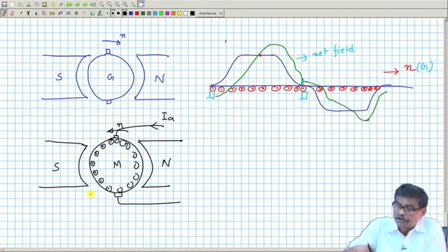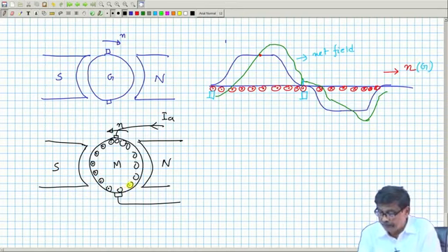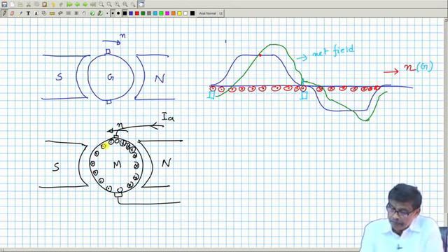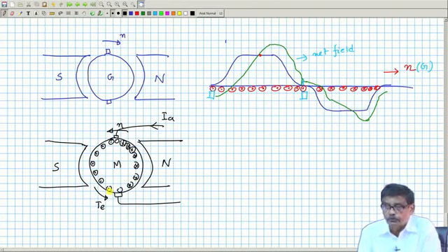It is the forced current into the armature in this direction, and the direction of the torque is in the direction of rotation. Apply the left hand rule, you will get that. So, this is for motor mode.